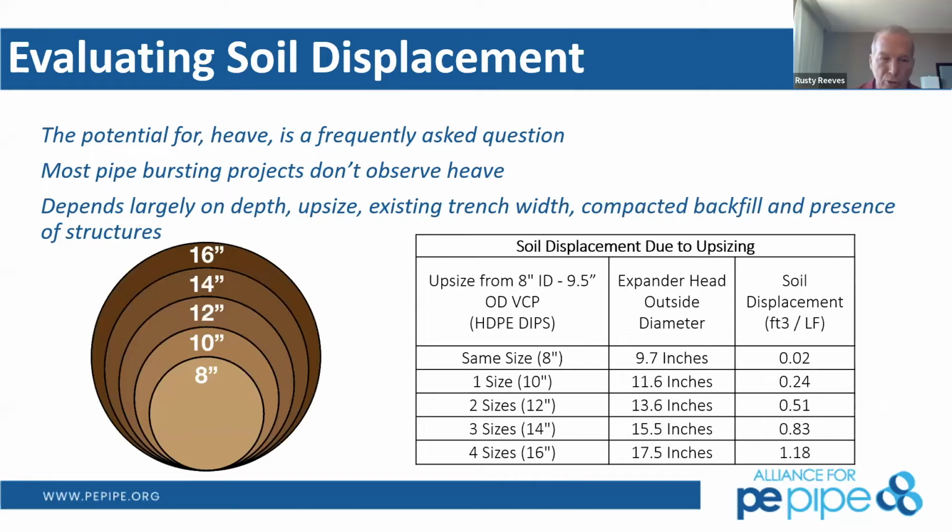Yes, Rusty. Yeah, I think you're touching on a lot of the material that was coming in the questions. There's a lot about displacing other utilities and shallow pipe going under concrete driveways, that type of thing. And really, it is very much tied to the material that you're going through. Like you said, a dense clay may not get a lot of movement, or you may have enough that you can push that to the side. It depends on the piping as well. And I know we had a question on doing same size or upsizing, and that's the same thing. A lot of those are going to be based on your project, the pipe material, the soil, and how close those utilities are.